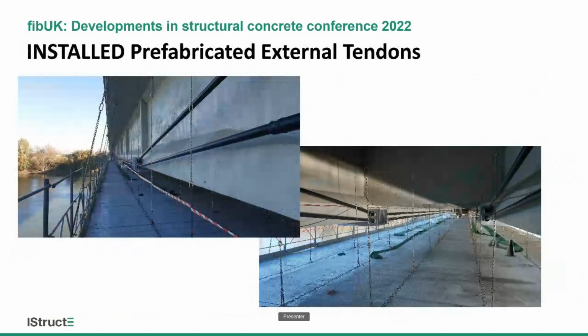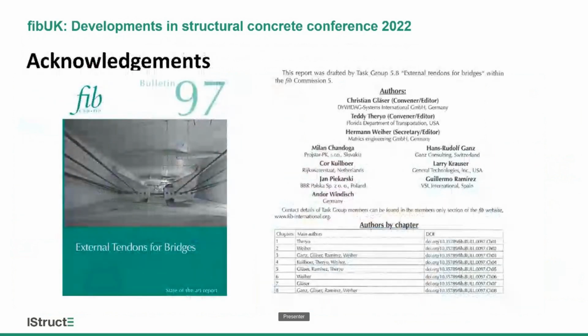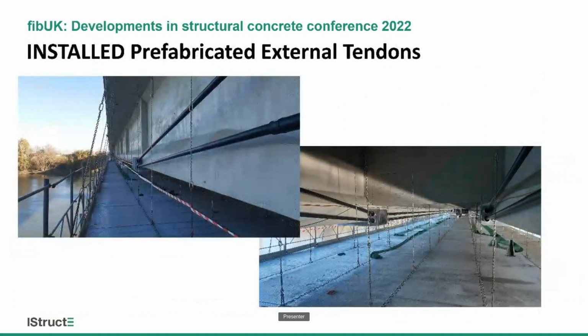After that, the project succeeded. All the spans had been equipped with the tendons, and the measurements of the deflection showed at the end that the target was achieved, and the bridge is now in a really good condition again and can be used for the next couple of years.